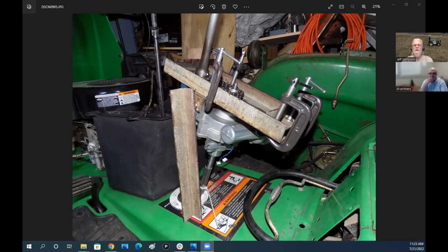So in order to solve two of those problems, here's the bolt that goes through. I've got the long bolt that goes through the motor to hold it in. So what I want to do is put these vertical plates, vertical angles here, and drill a hole here and bolt it on. And then down here, put a piece of angle iron across here and bolt it down to the floor pan, and then weld this one onto that piece of angle iron on the bottom.